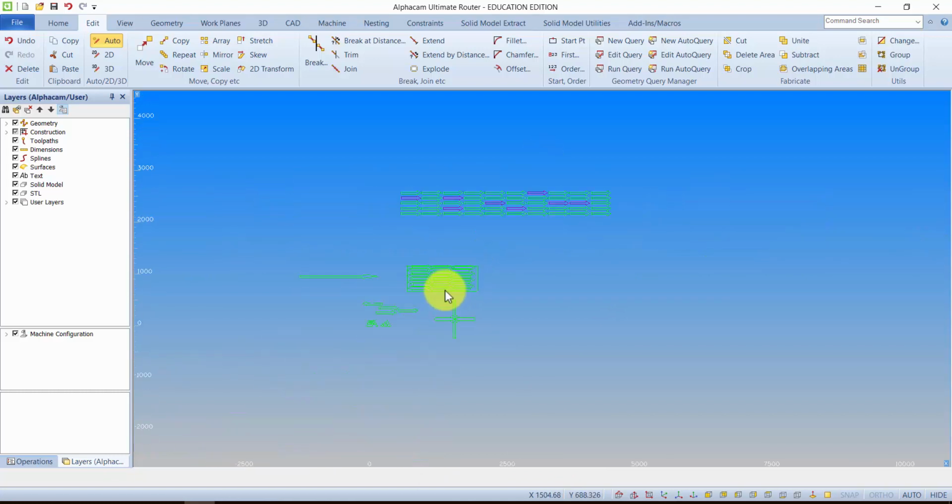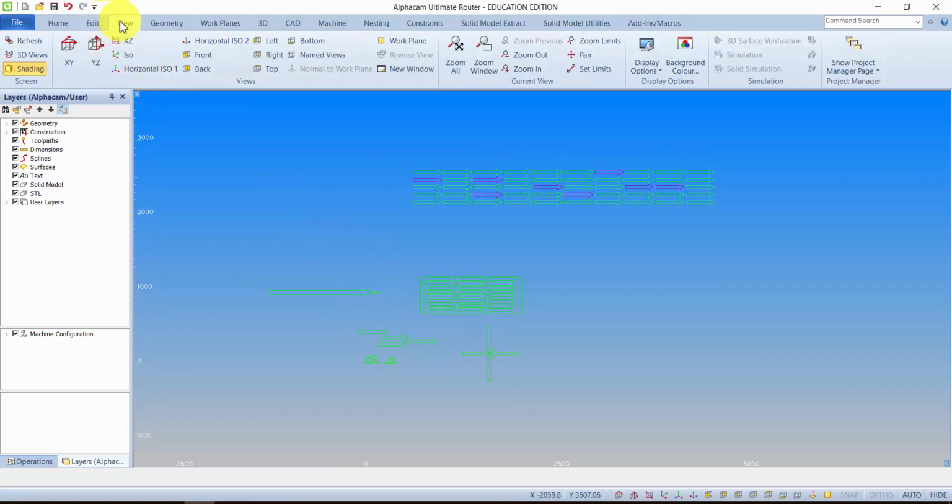Now just before we finish up, I want you to also explore the view command. We haven't looked at that in a while. If I go to XY, it's what we're on now. If I go to YZ, I'm looking in at the edge of the thin sliver, the plane that I'm drawing on. XZ similar, but just a different direction. ISO, I'm looking in 3D. Some people prefer to draw in ISO. I find it a little difficult to get my perception and my bearings as to what's horizontal and what's vertical. So typically, we're looking at the XY or the top.